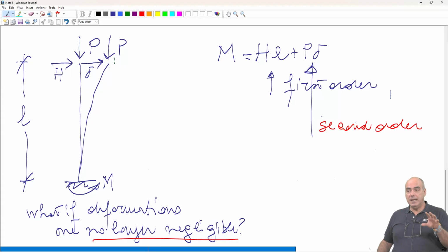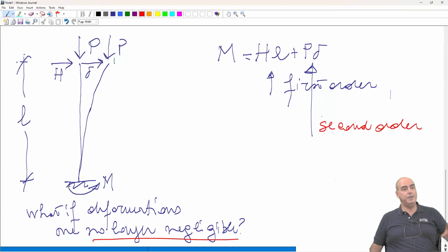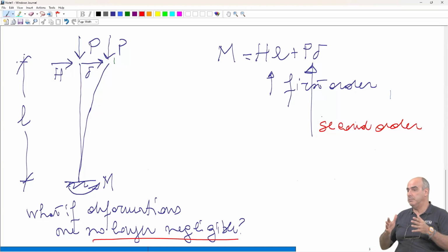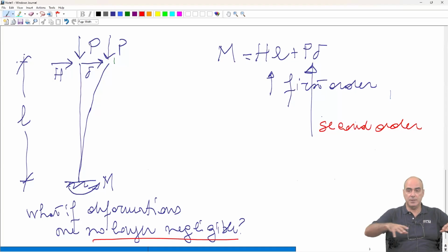But you see, in precast structures, we have said that one of the advantages is that because of the better strength and better quality control of concrete, and because we cast horizontally, so there is better quality control of elements, we can have more slender cross sections. But more slender cross section means that delta is higher.